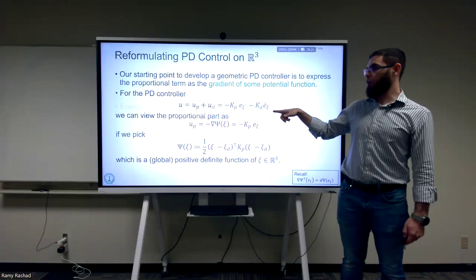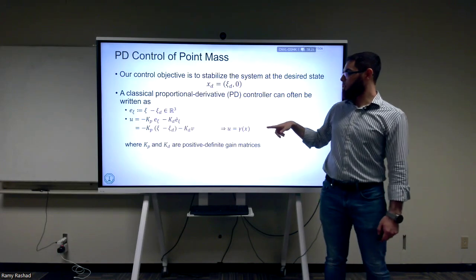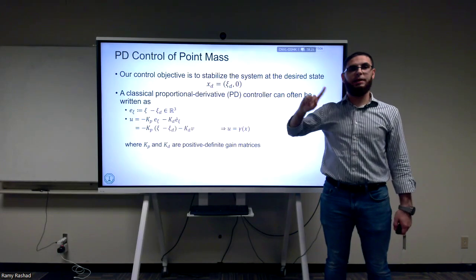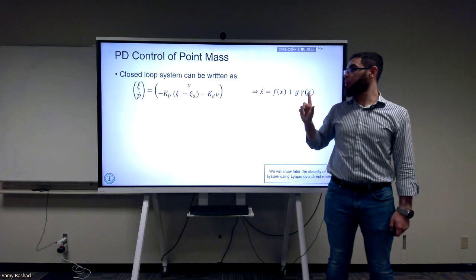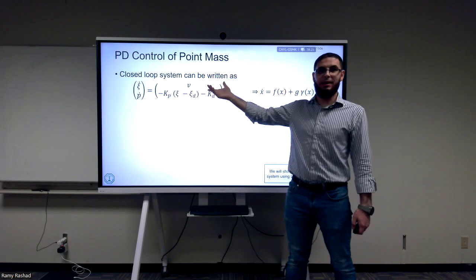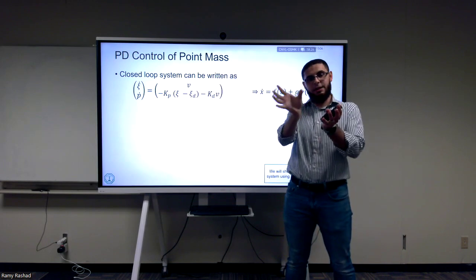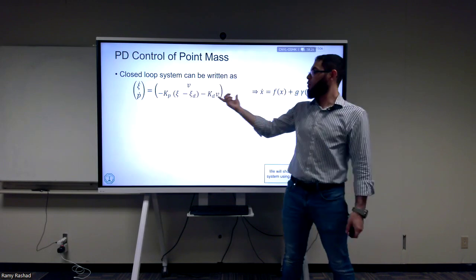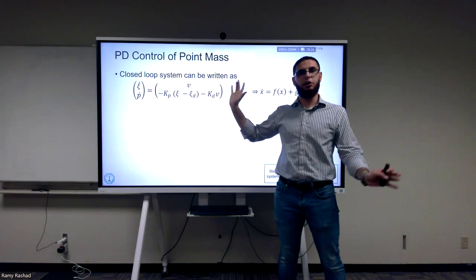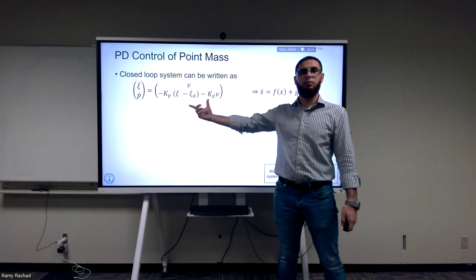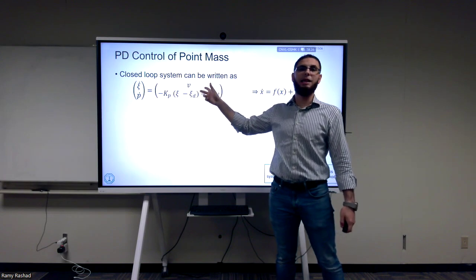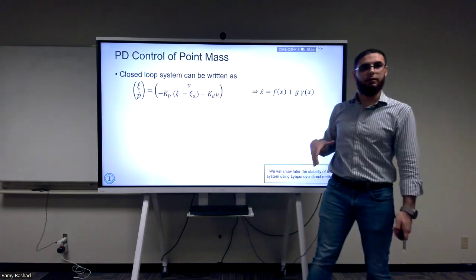So, okay, to go back here, this is a linear PD controller. Okay? A linear PD controller. And I had a linear dynamical system. When I took the linear controller with the linear system, what was the closed loop system? Linear. I composed a linear with a linear, I got a linear system in the end. So this is A minus BK, something like that.